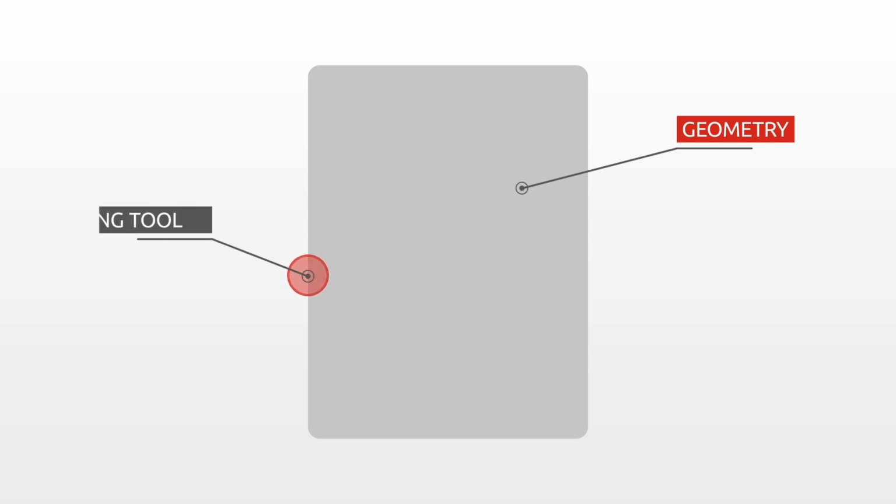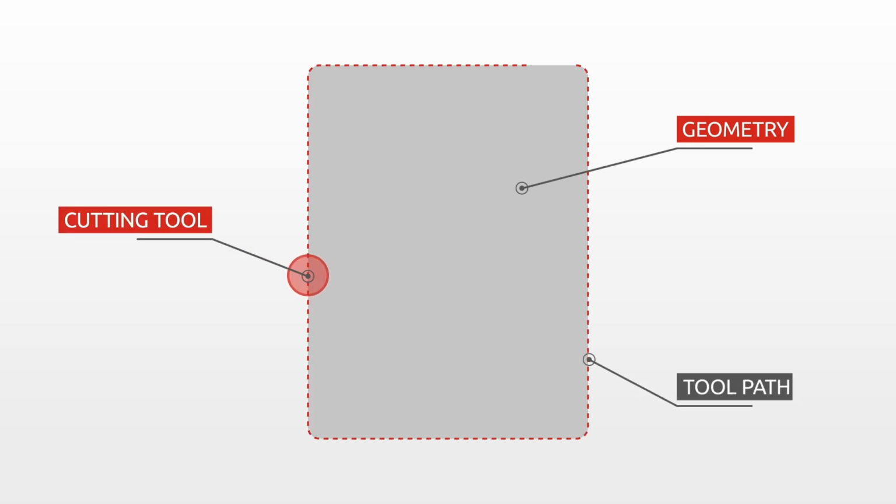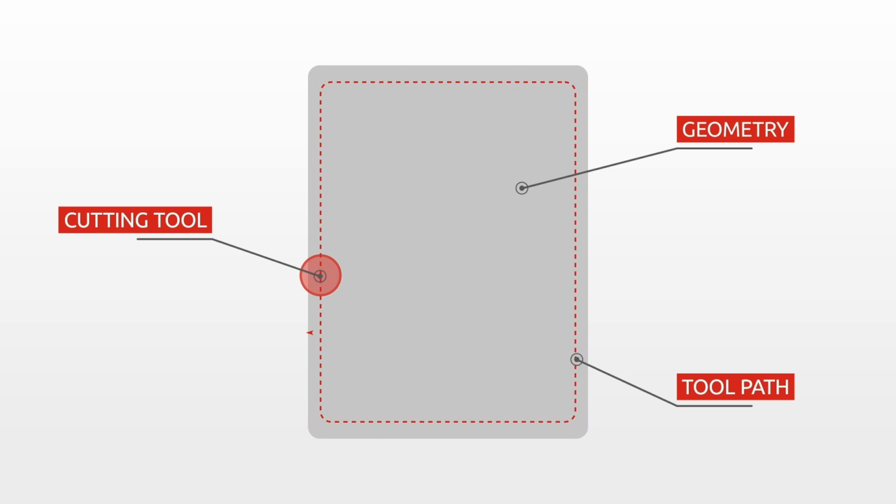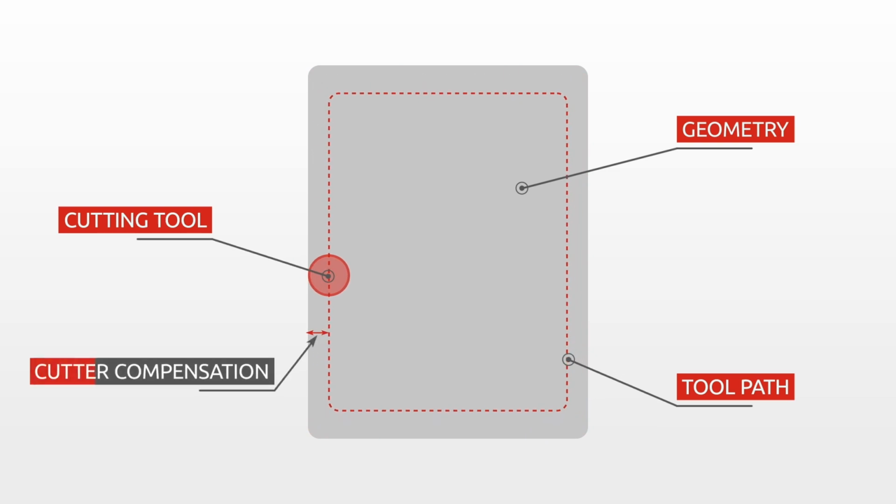It allows the user to have the toolpath centered along the feature as opposed to the tool itself, therefore removing the need to manually offset the tool so its outer diameter is flush with the outer face of a pocket, for example.